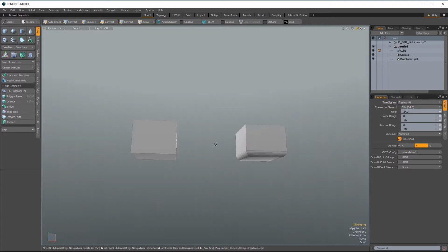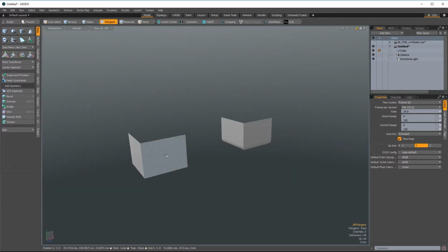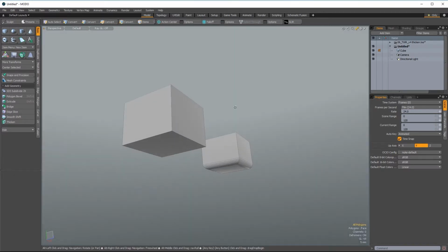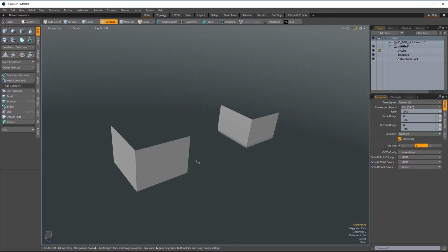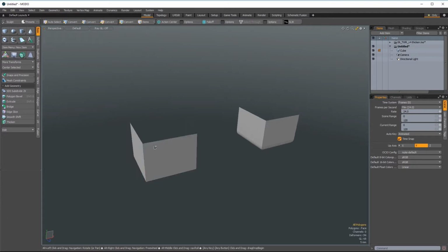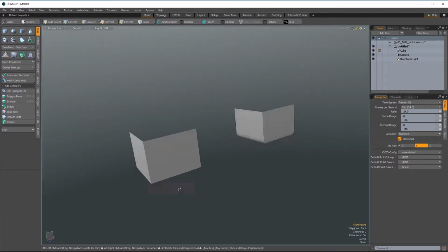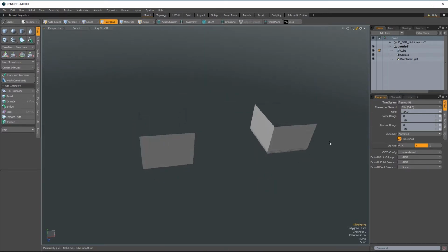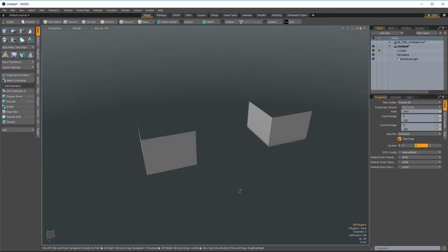I want to note something about polygons, speaking of. It's something that you've probably already noticed, and that is polygons are single-sided, which is why they are opaque from one side and transparent from the other. This is an important concept to internalize, especially if you plan on building models to export or to use in 3D printing. You're going to need an airtight model.